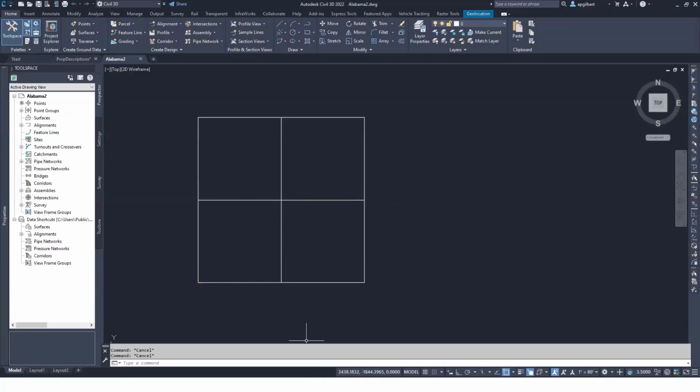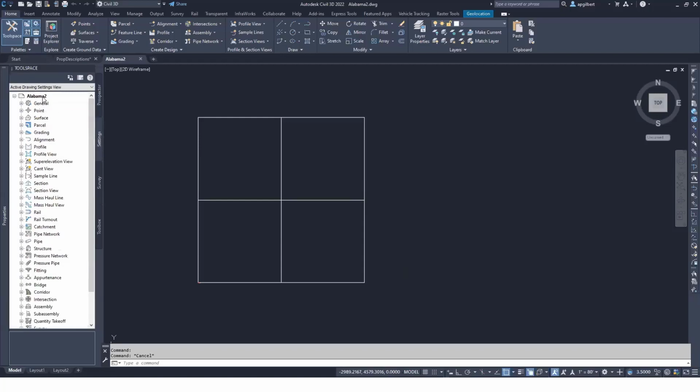Okay, and so if you look at the cursor, my running coordinates here, this is down around the origin or 0. This is basically polylines, and this is 1 mile by 1 mile. And it's splits. You can see the half-mile points. And what this represents in Alabama, we have the rectangular planar system for all of our property is referenced to that, the public land survey system. And so I just drew a quick 1 mile by 1 mile to do some of my calcs for my boundary work.